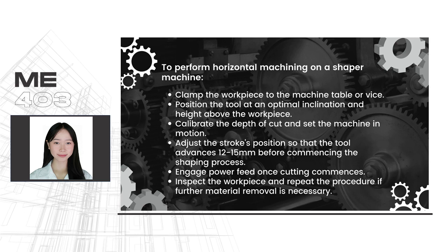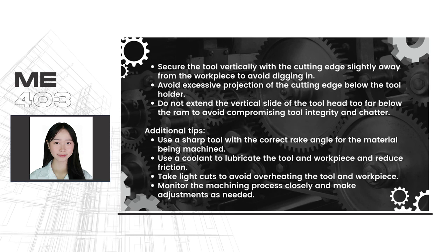Fourth, adjust the stroke's position so that the tool advances 12 to 15 mm before commencing the shaping process. Fifth, engage power feed once cutting commences. Sixth, inspect the workpiece and repeat the procedure if further material removal is necessary. Seventh, secure the tool vertically with the cutting edge slightly away from the workpiece to avoid digging in.